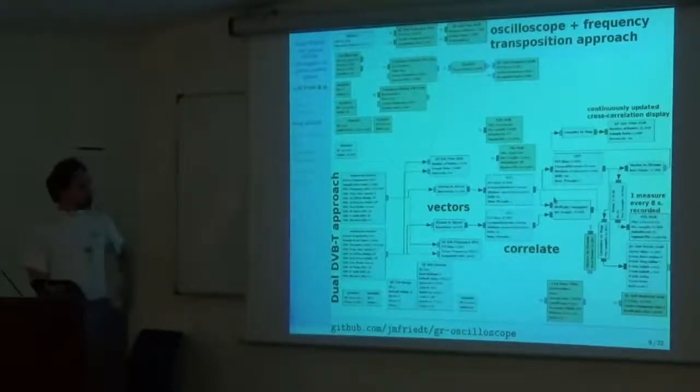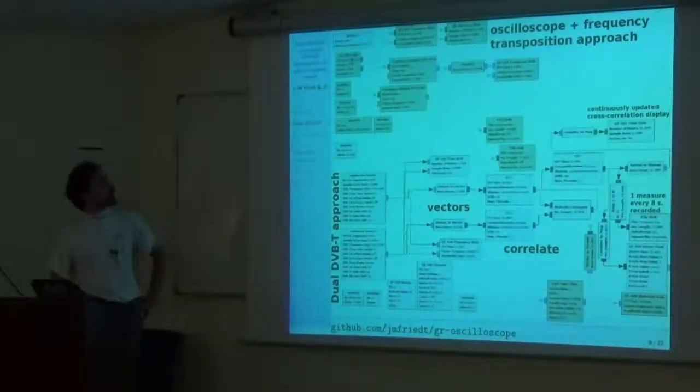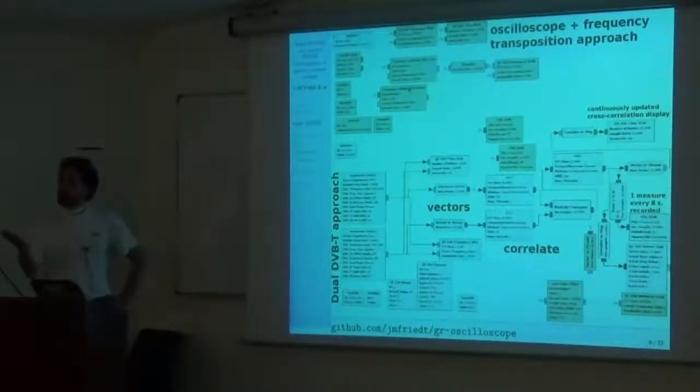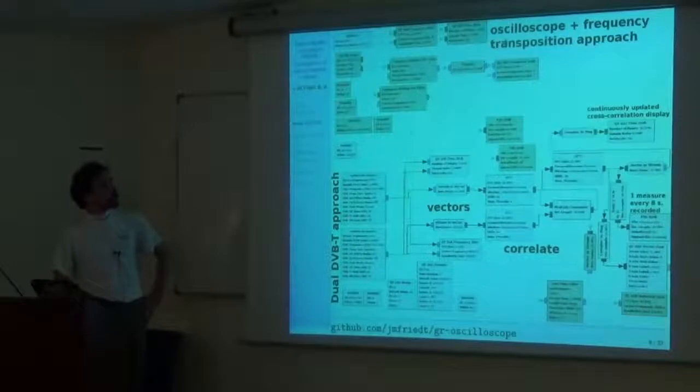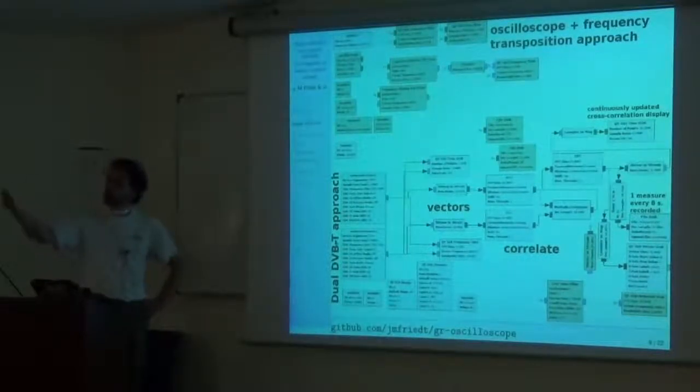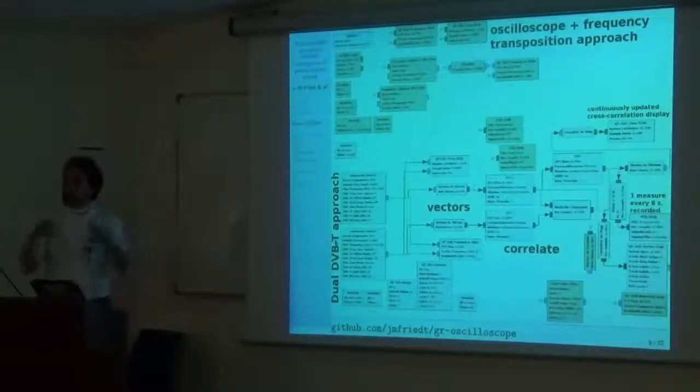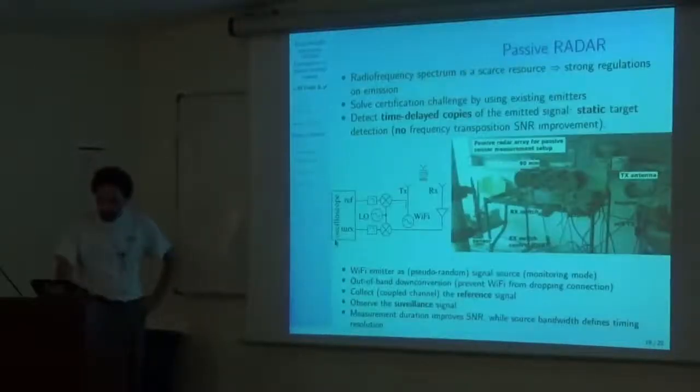And what I like with GNU Radio is that you will run the same flowchart with either. This is my passive radar implementation using DVB-T receivers. We discussed it with a few of you during the demonstration. You can have the €6 DVB-T receivers as signal source, you can do the same with an oscilloscope, or you can do this with a synthetic signal. The flowchart is exactly the same. You just have to adapt the source to whatever signal you want to analyze. That's an example with an oscilloscope, that's an example with DVB-T, and tomorrow during the tutorial, we'll do the same with a synthetic signal. That's really the beauty of the GNU Radio flowchart: it can also run on a synthetic signal to test your signal processing techniques.